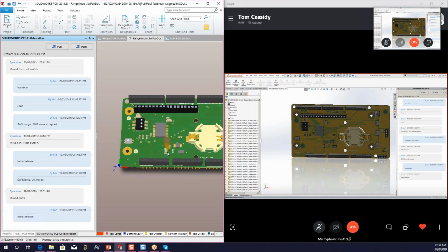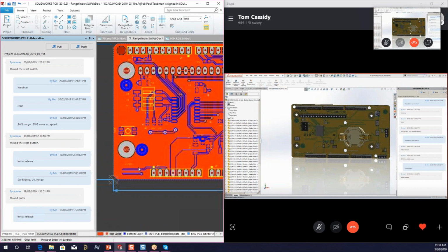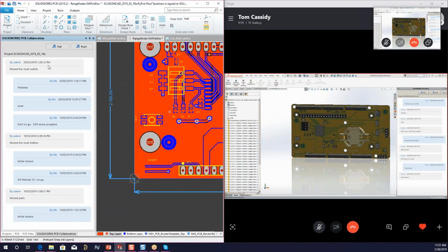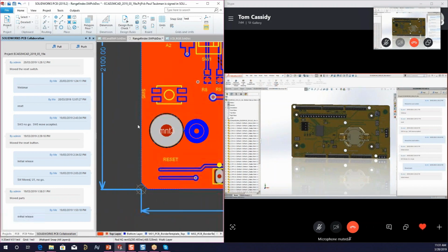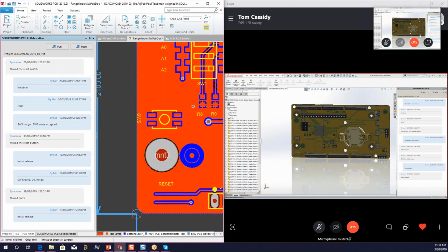I'll say repour it, and that's fine. So you can see that change here once we do this. Now, of course, keep in mind, the way we have this set up over here, if I hit the 2 key, it did get moved, and it's now been locked in and recorded here. It's just that my routes would have to be moved at this point in time, and there'd probably be some issues with some shorts. But for our demonstration purposes, this will work just fine.